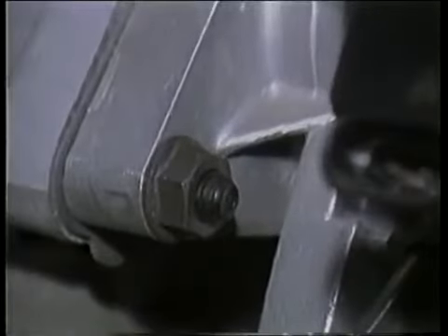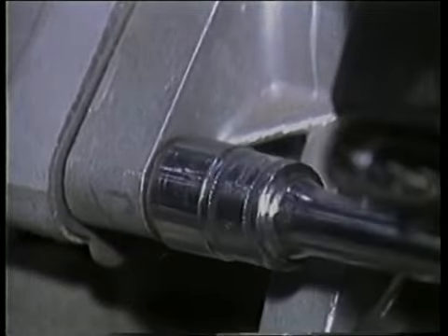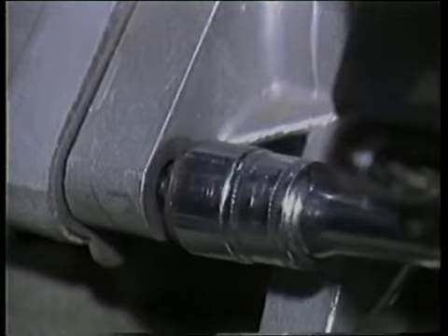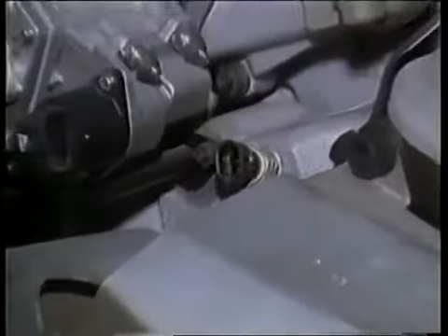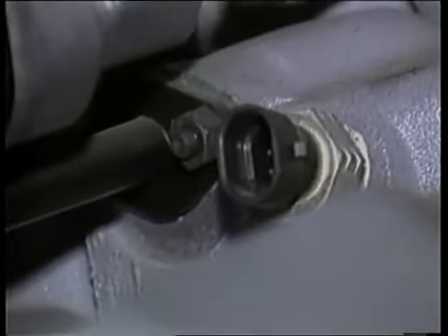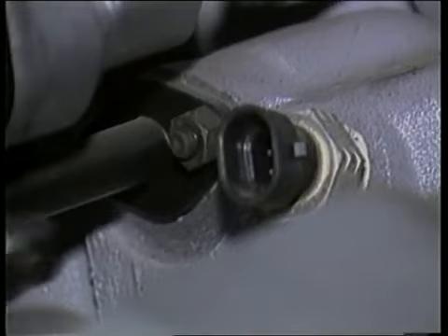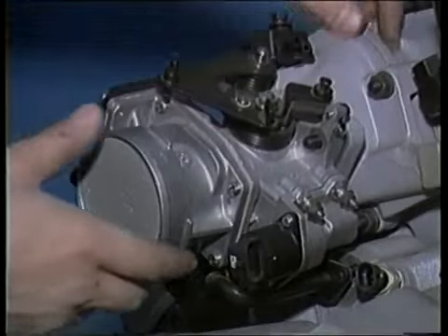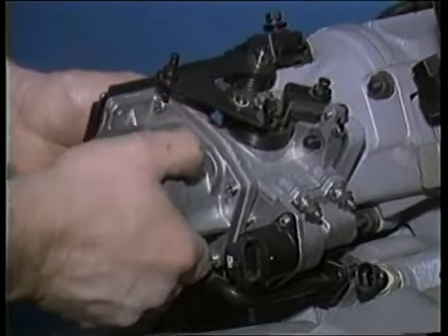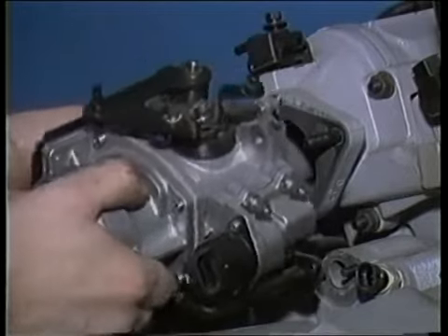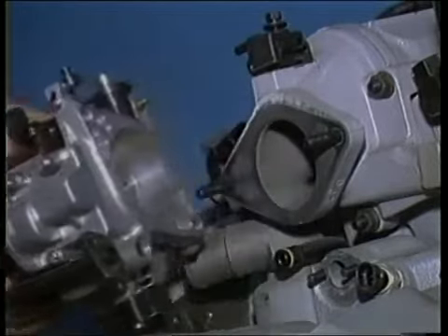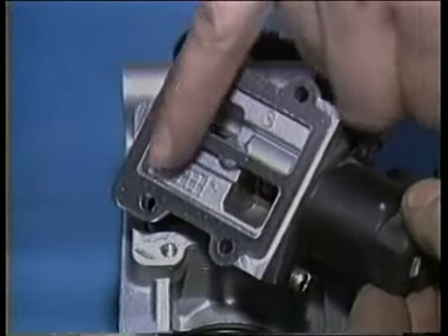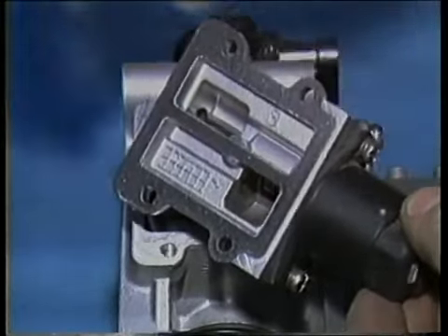Remove the fasteners that secure the throttle body to the engine intake manifold. A socket and extension is usually the best way to reach the nuts or bolts holding the throttle body. Before attempting removal, double-check that everything is disconnected and out of the way. Wiggle and pull to free the throttle body from the engine. If vacuum leaks are found before removal, install new gaskets and also use a straight edge to check for surface warpage.